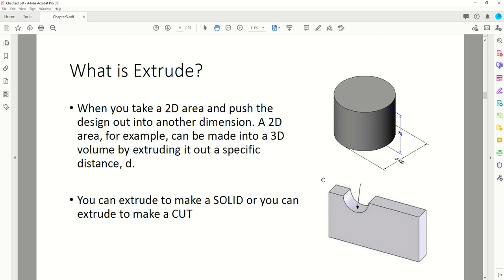So you might be asking, what exactly is extruded boss/base? Essentially, we use the extrude to make a 2D sketch 3D. So in this example, we could draw, in 2D, this circle with a diameter of 100, okay? And then we'll use the extrude feature to actually make this cylinder. So we would extrude this circle by 75 to create this cylinder here.